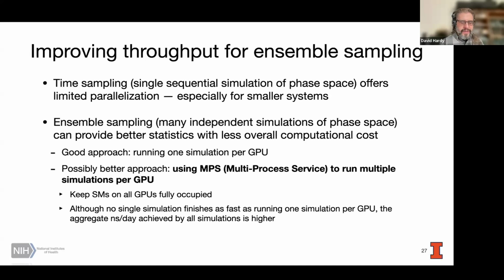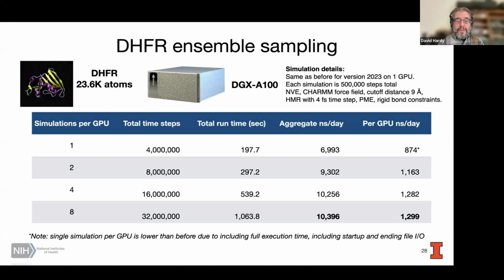And the idea is just to really keep all of the hardware on the GPUs busy, keep the streaming multiprocessors fully occupied. And so, although no single simulation will finish as fast as running one simulation per GPU, the aggregate nanoseconds per day that you can achieve over all of your simulations ends up being higher. Let me just show you some data to give evidence to support my point here.